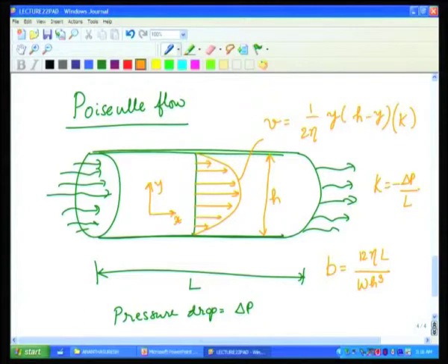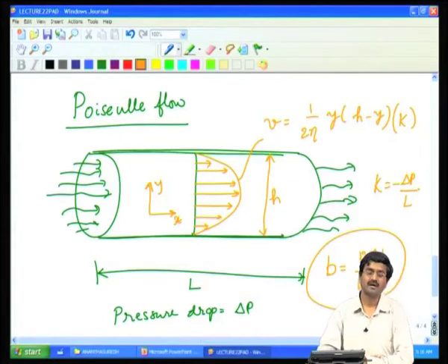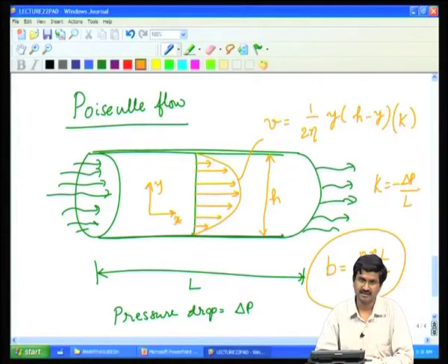So, in the pipe flow like this, that is your damping coefficient, and you can take that into a formula in the lumped modeling and do the dynamics, okay. If you want to do the full analysis, like we do 3-dimensional analysis for an elastic solid body, here you have to use fluid dynamics equations, where we have to solve the so called Navier-Stokes equations and get the result. There are a lot of finite fluid simulation software programs out there, any one of them can do it, or it is always better to take a sample problem, a small problem, and try to code it ourselves.